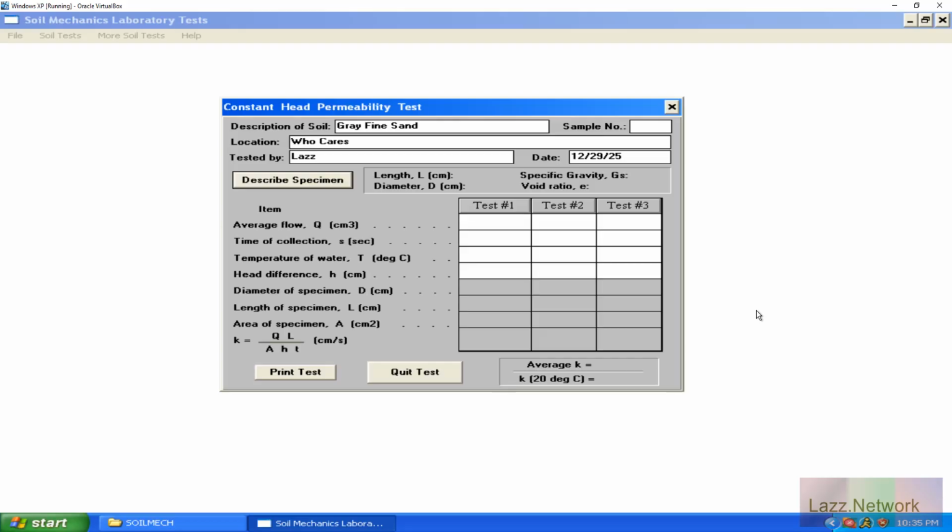Technically the most accurate way is the first way, like I indicated, using a manometer, because it's actually measuring the flow rate of the water inside the sample at the most center point of the sample. So it gives you the most unbiased reading for what your actual head difference is in your specimen.